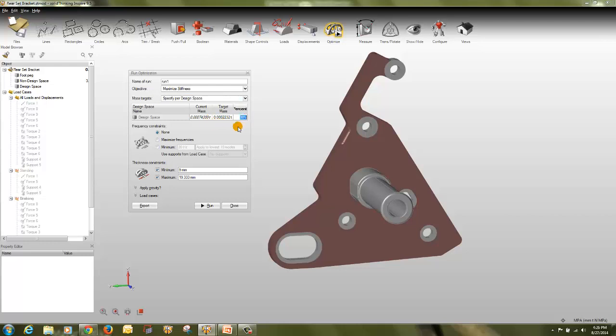So you can put a percentage like 40%, or like 10%. Or you can enter the target mass in kg. It's 0.74 kg, so 10% of 0.74 is this, 50% is this. So it will keep this, the rest it will remove.